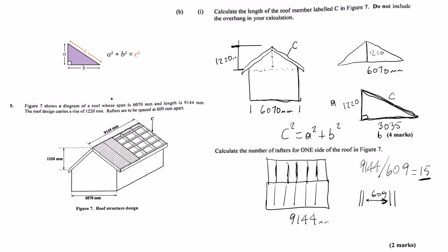Plus, you often add one extra for the end, depending on how you measure. But the calculation gives you the number of spaces, essentially. Okay, so 15 spaces means 16 rafters usually, or 15 plus the gable end framing. Something like that, yeah. The key is the spacing is determined by things like the load the roof needs to carry, the strength of the timber.